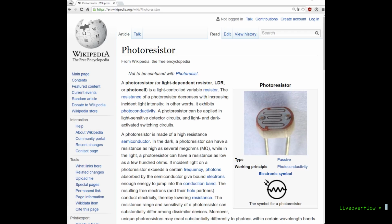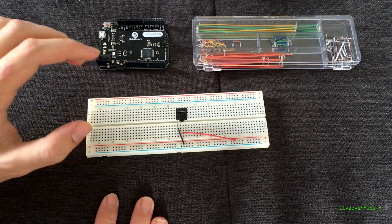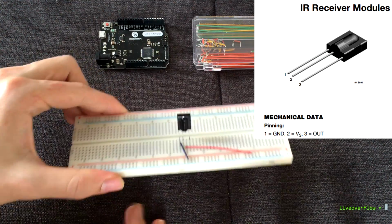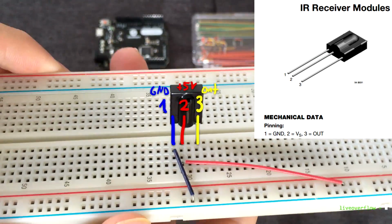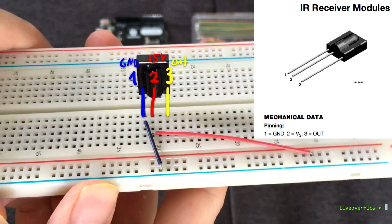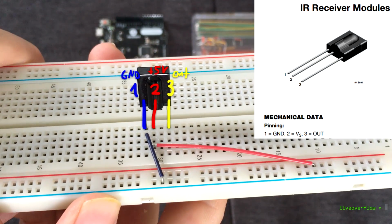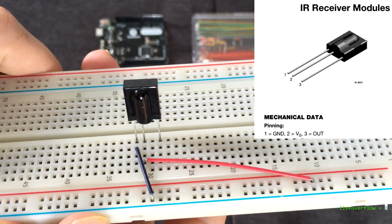There are light sensors, so-called photoresistors, which increase or decrease resistance depending on the amount of light. Though this one is calibrated for regular visible light, so it's no good use to us. But I have here this IR receiver, which works more like a transistor. It has 3 pins. 2 pins are basically the power supply, plus 5 volt and ground, and the 3rd pin is either high or low depending on if it captures a significant amount of IR light or not.